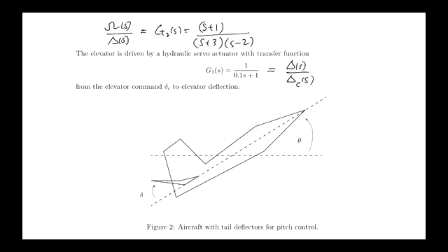Or even if it were over here, then it would flip down. So unless the centre of mass is exactly on the axis of rotation, this is unstable. And aircraft are often designed to be unstable, to make them very manoeuvrable and fast. Okay? But in making them unstable, they become hard to fly.